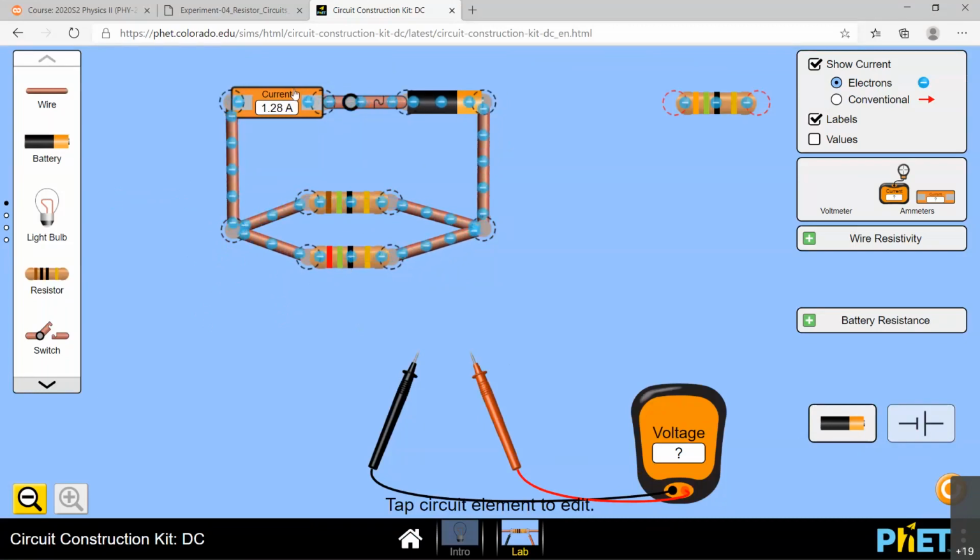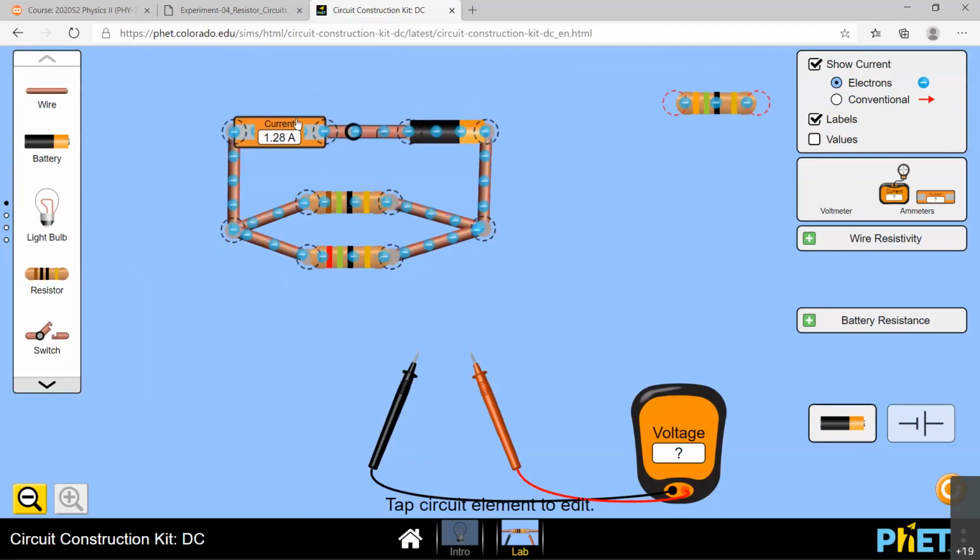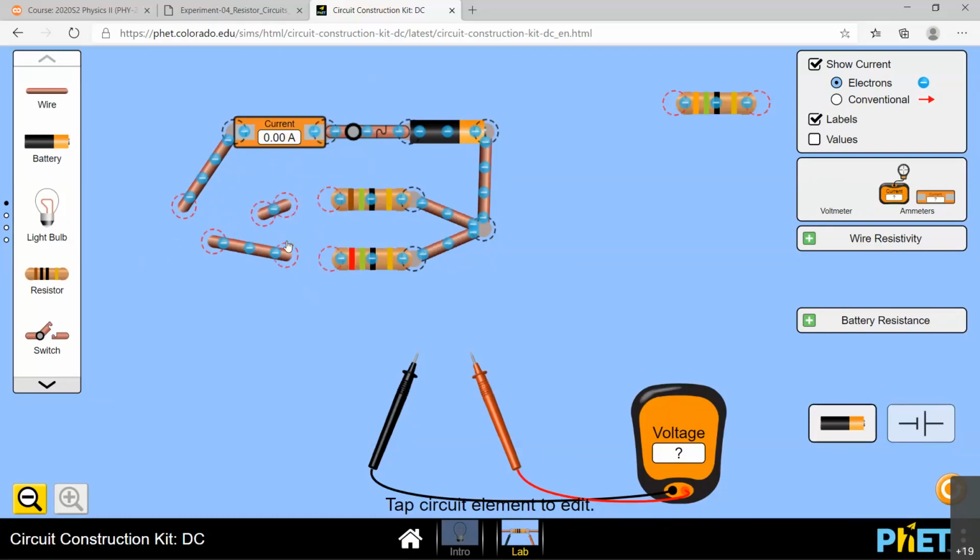All right, so question. Now we have a parallel circuit for case 1. Now when you measure the current for the parallel circuit, this current is also important, that is the total current, but we need the current passing through each resistor, which means I need to break this point here. I have to apply two other ammeters across each resistance, right? Since this is a simulation, you can bring any number of items without any problem.